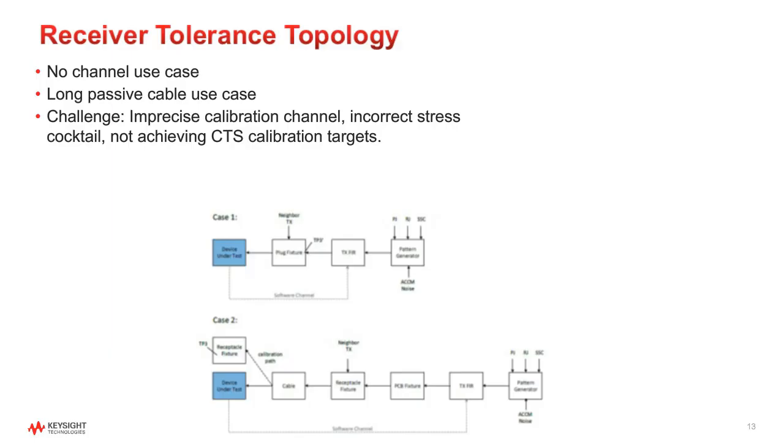In the USB 3 world, we had a whole bunch of additional software tools that help with something called link training, which is the steps required to go to the LTSSM state to get that data into loopback. USB4 silicon is required to have the error detector built in, and the USB4 receiver methodology requires that we put the product into the BERT testing mode directly without going through the sideband LTSSM.